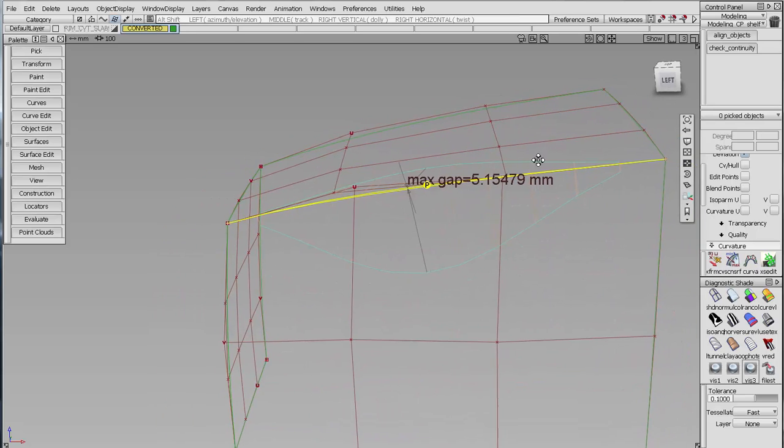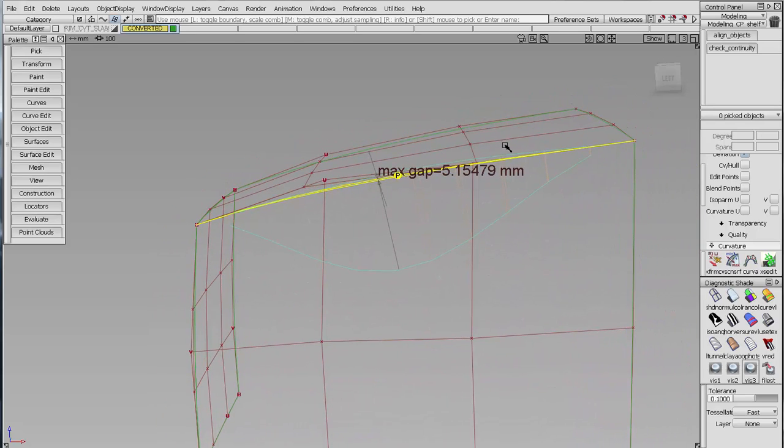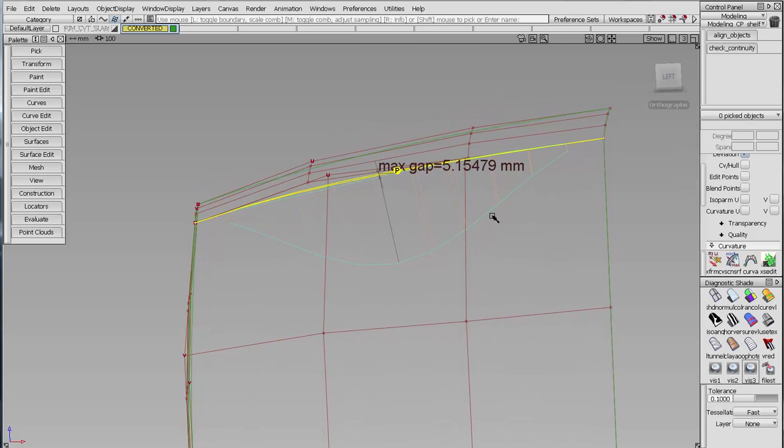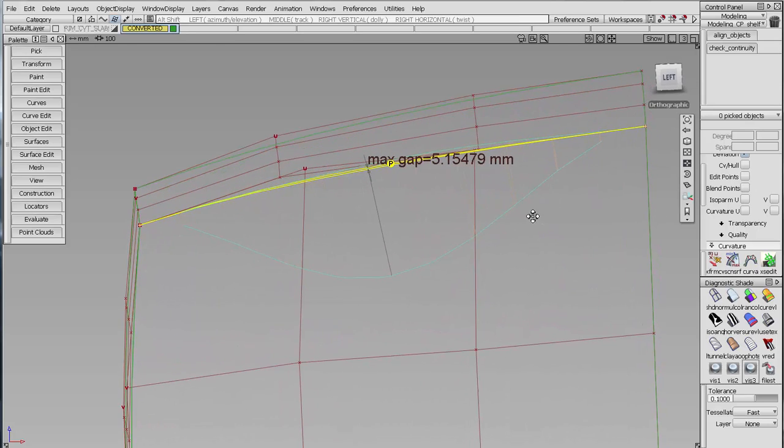And if you look at these CV locations, and just to be a little more precise, it's hard to tell if things are parallel and how they move when you have perspective. In this case, it looks like this row, and this row, and this row are all converging at a point somewhere over here. But if I turn off perspective viewing into orthographic, now we know that those are parallel. This is a key concept for, I think, analyzing CV structures, which is what we're going to talk about quite a bit.